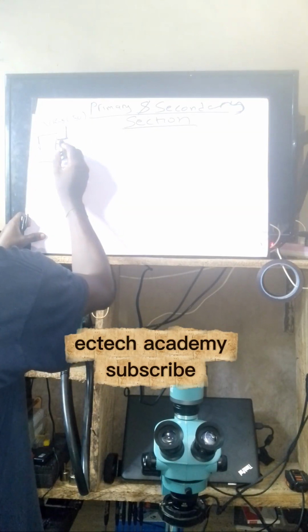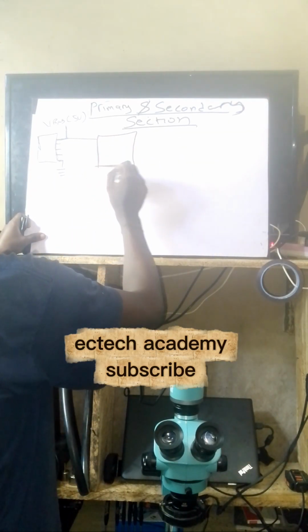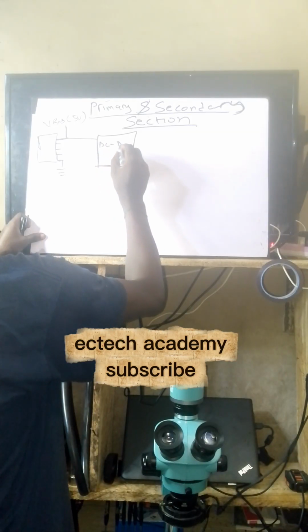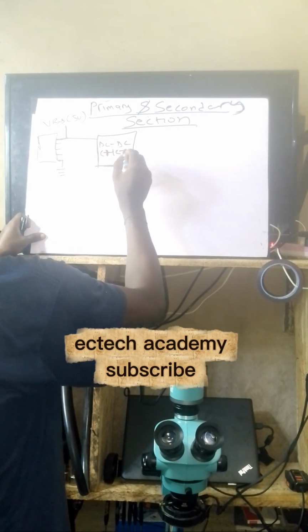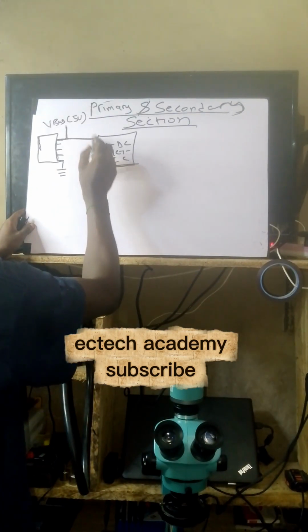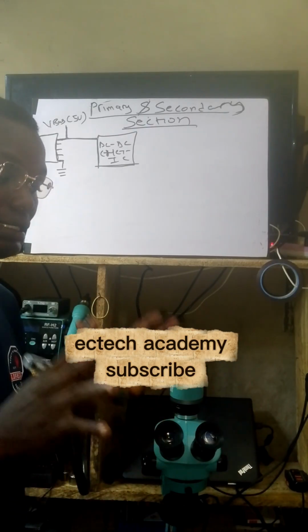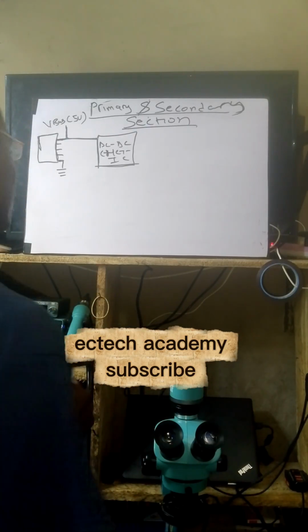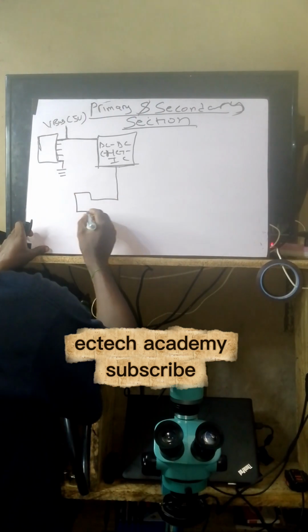This 5 volts, the VBUS coming from our charger, is going into the input of a DC to DC IC. You can also call it the charging IC. That's the input voltage for the IC to start working. After that, the charging IC will give out the output voltage, which is going to your battery connector.